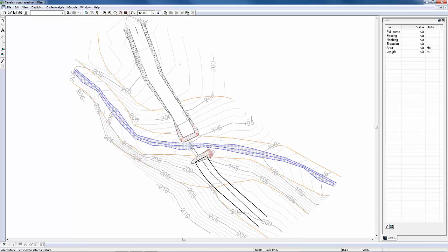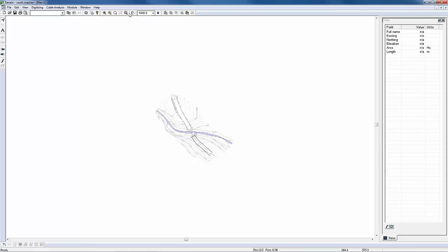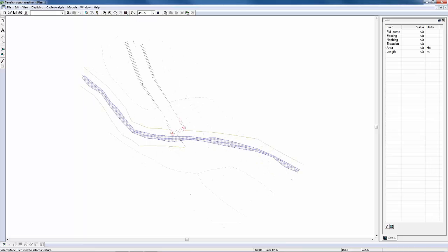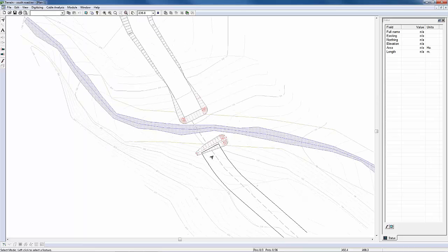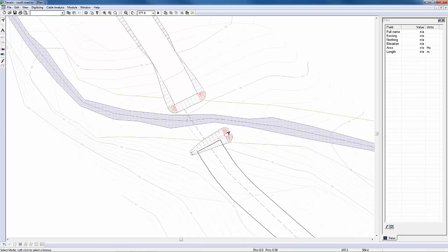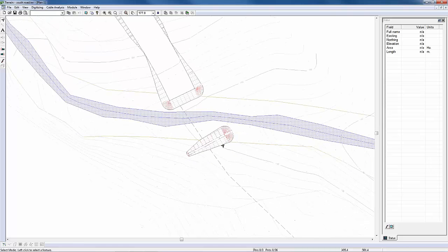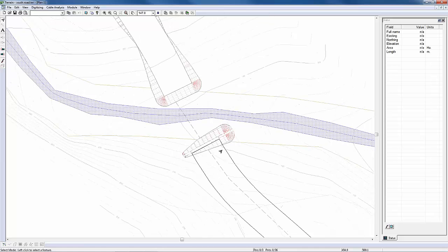And then I'm going to, let's just turn off the lock zoom, zoom in. I'm going to grade this down to the ground so that it basically grades around the new abutments. This time I'm going to grade to the left side.